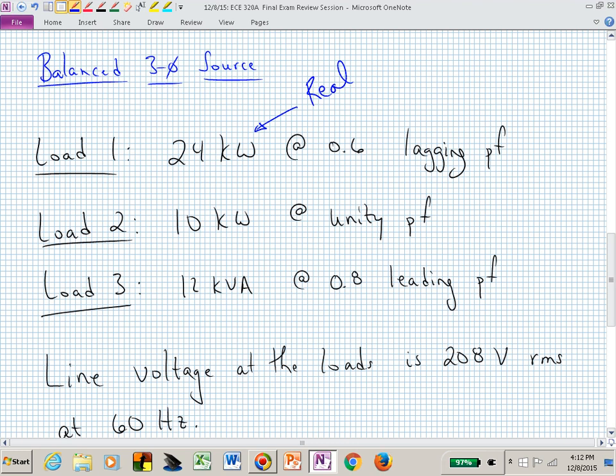Yes, because you have a power factor. So you do have a vertical or a reactive component. And in what direction is Q, the reactive piece, is it positive or negative? So from this, you have a theta. Is it positive or negative? It's positive, which says Q is positive.